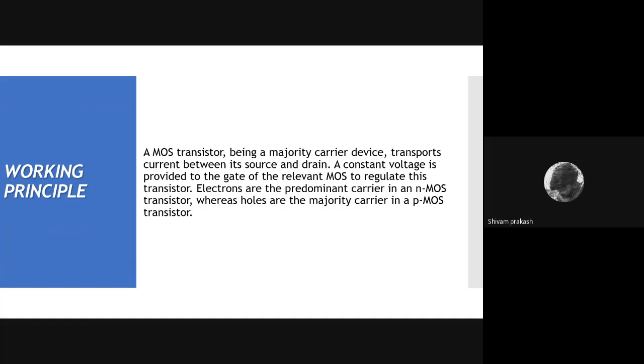The conductor makes up the top layer of the MOS structure. It is excellent for carrying current, and it is commonly referred to as the gate. Metal gates were employed in the first transistors, but as time proceeded, the transistor gate was changed to polysilicon. A thin insulating film of silicon oxide forms the intermediate layer of the MOS, commonly referred to as the gate oxide, and silicon is doped in the layer at the lower level. When we supply a negative voltage to the gate, it attracts positive charge as the mobile carriers, and the charge with the energy moves outside the gate and the holes.